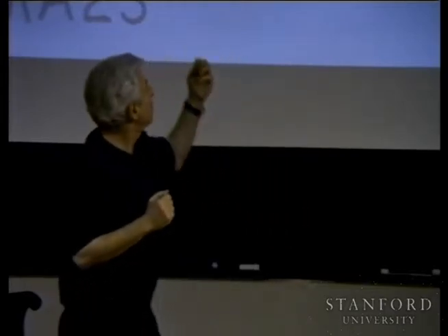So the inertia viewed from a joint is going to depend on the structure following that joint. And we will see that essentially all of this will come very naturally from the equations that will be generated from the multi-body system. But all that we are going to use for this is a very simple description that, again, will allow you to take a look at this robot and say, oh, these are the dynamic characteristics of this joint, and you can almost see the coupling forces between the different joints in a visual form that all depend on those axes of rotation and or translation of the robot. And this comes through the explicit form of dynamics that we will develop.